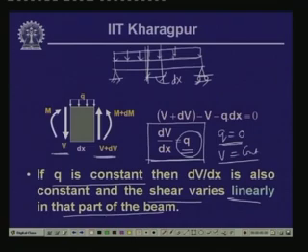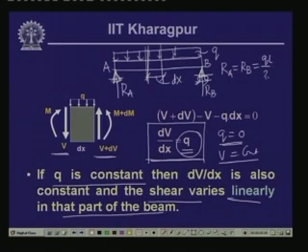In fact, if you remember, for a simply supported beam with q as the uniformly distributed load, since we do not have any horizontal force, the reactive force which we will have at this hinge support is a vertical one. If we call this end A and this B, this is R_A and this is again a vertical support which is R_B, and this being symmetrical, we can write that R_A is equal to R_B is equal to qL over 2, where qL is the total load. So, half the load will be carried by reactive force A and half the load will be carried by reactive force B.